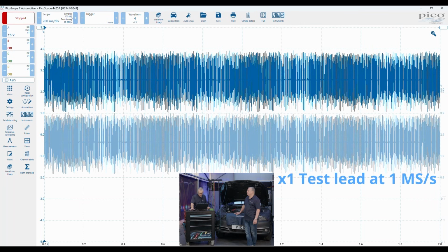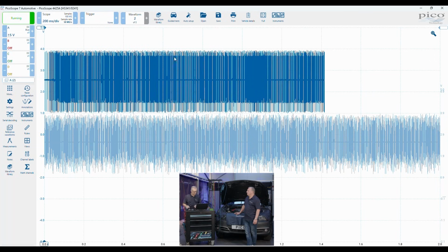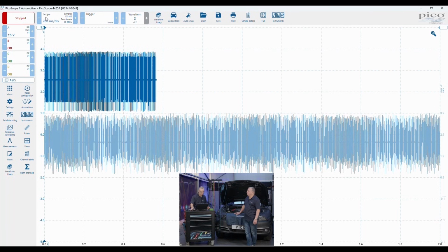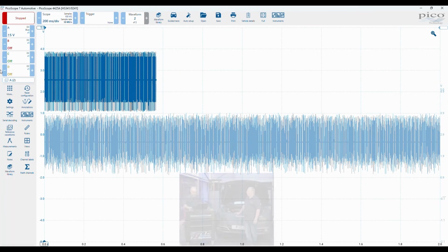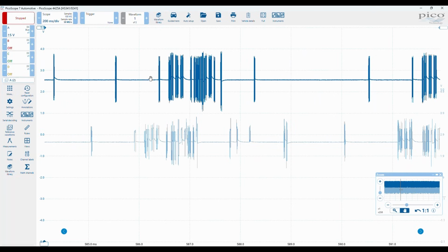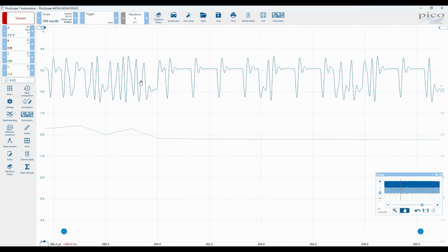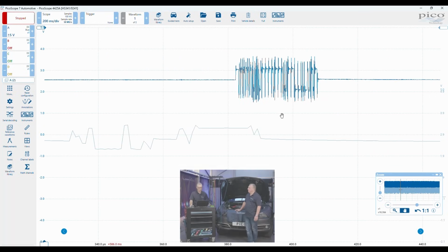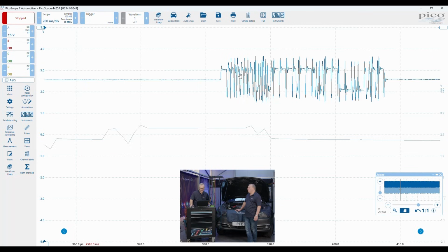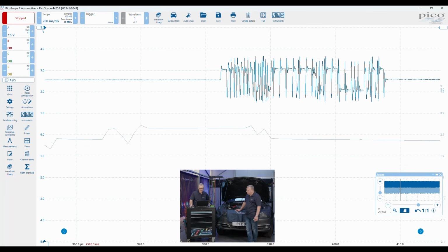And let's just drag this down here, and now we've changed the sample rate to 50 million. The vehicle has gone to sleep, so let's just operate the remote, wake the network back up. It looks better already. Sorry, let me move those out the way. And we'll zoom in. So it's now looking much sharper in terms of edges, almost like it's starting to form a packet, I would say. You can almost see what's going on there, but there's an incredible amount of ringing noise.